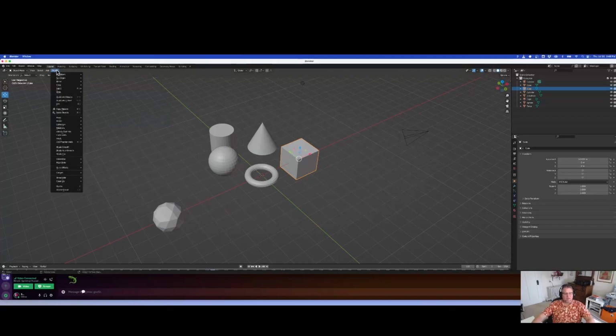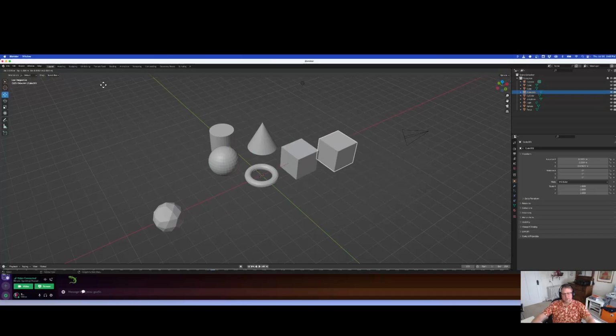The fastest way, or the first way that I'm going to show you, is to do a duplicate object, which is right here under the object menu. So select the object you want to duplicate and duplicate object. Then as you have it, you can just start to move around and you've got that same object. Notice up in the outliner, it's given it a second name, and it usually gives it 2 zeros and a 1.